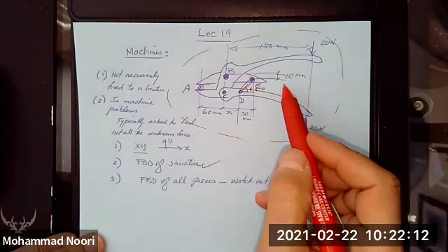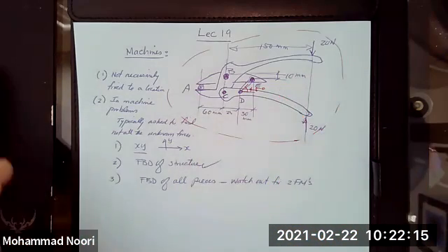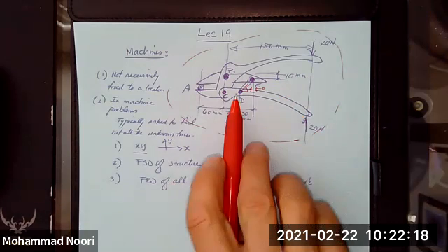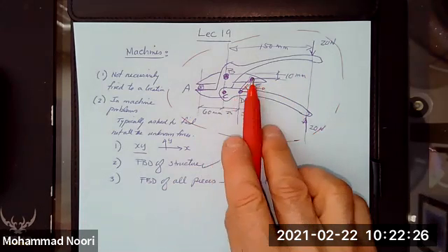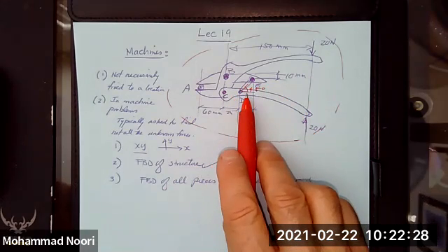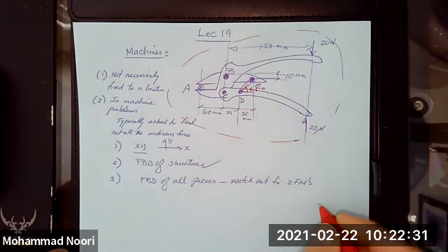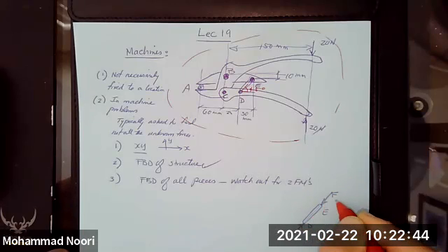First of all, do I see a two force member here? Of course I do. Look at member DE, connected only at the two ends, right? The two ends are pins and no load acts along that member. So if I start with that, this is member DE, and let's say forces that act along a line connecting these two is F, equal and opposite in direction. So that's the first free body diagram.